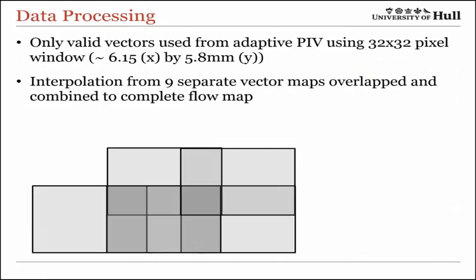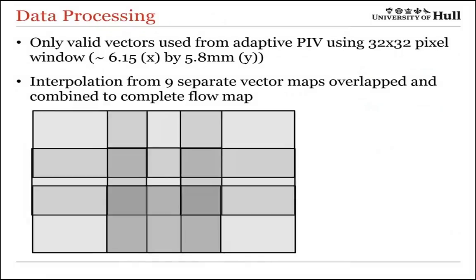And what we essentially did is then do that over a series of panels. So this is where the rotor is. We did this over a series of panels that we stitched together by moving the PIV camera and laser domain up and down. We also did some lateral things as well that I won't talk about today. But that essentially gave us this much bigger domain where we were quantifying the properties of the flow field in the wake of the rotor.